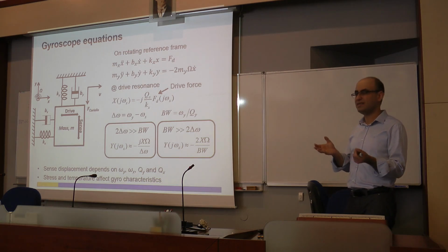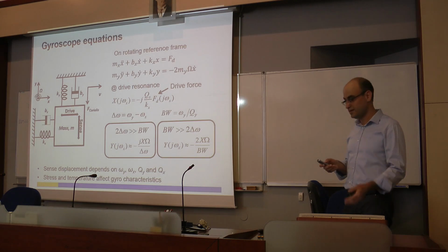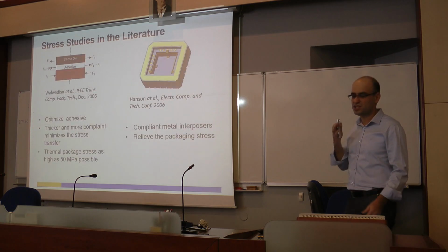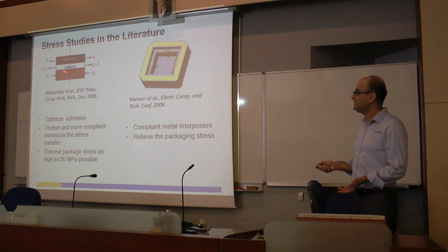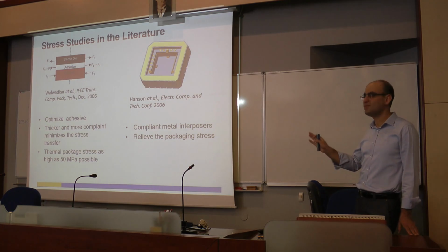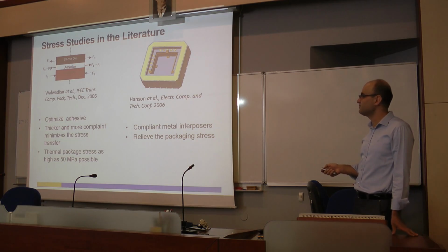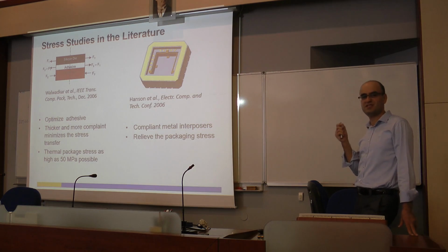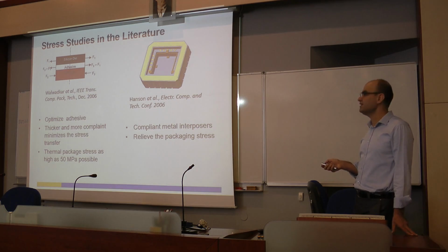Stress and temperature modify the resonance frequencies, modify the gaps, modify the quality factors, and that results in an unwanted shift in the output. And stress has been studied. As I said, the die attach, so this is your sensor and this is your package, for example. This is the same for all ICs. It's manufactured on silicon and it's somehow mounted somewhere. And you use an adhesive, and the properties of that adhesive, not as important in the IC industry, but it's very important in the MEMS industry. Because this adhesive is basically determining how much external stress comes into your die.